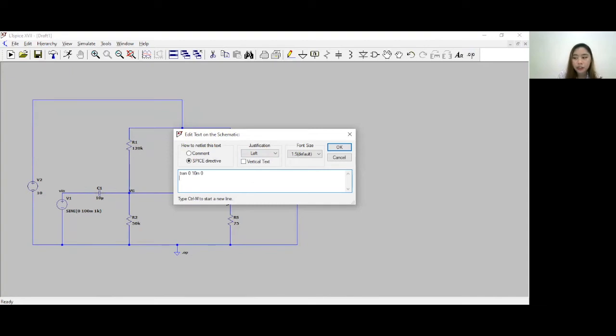I will use for the voltage output peak to peak and the voltage input peak to peak as VOPP, Vout, and then .meas VIPP, PP, V(in), since it's a voltage in.